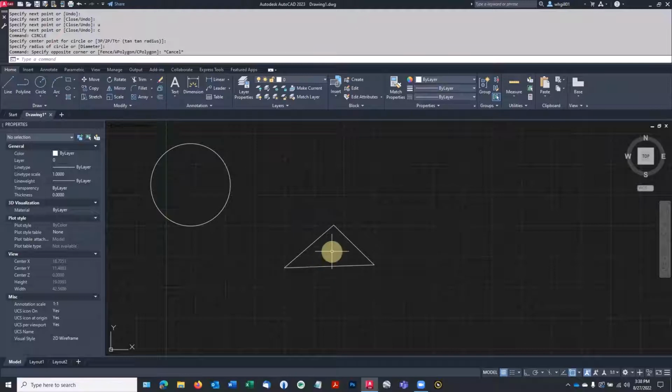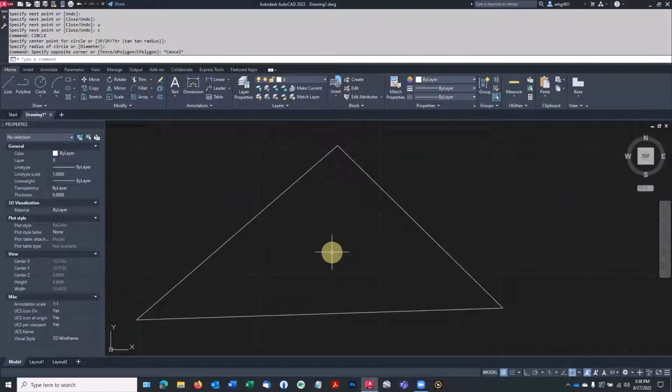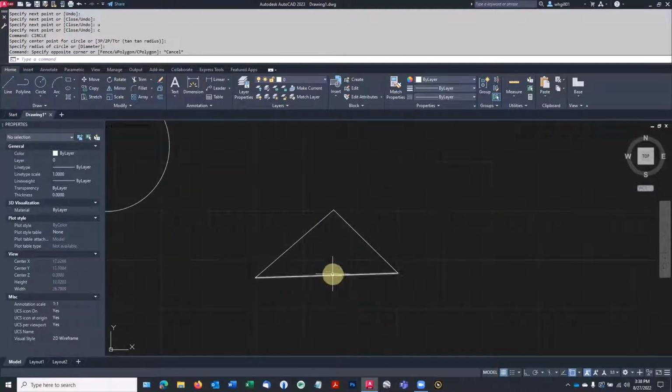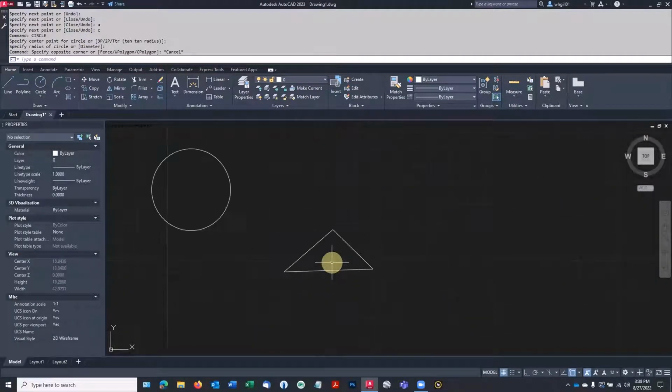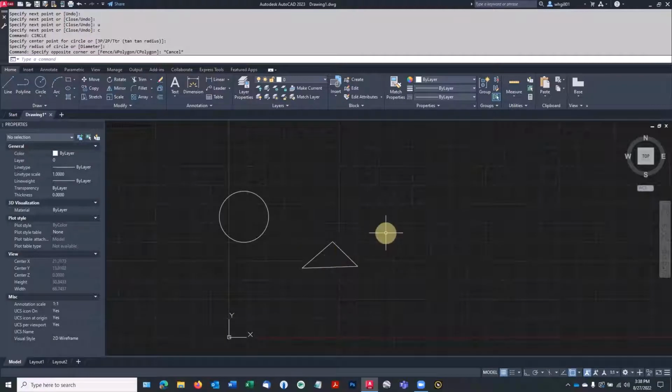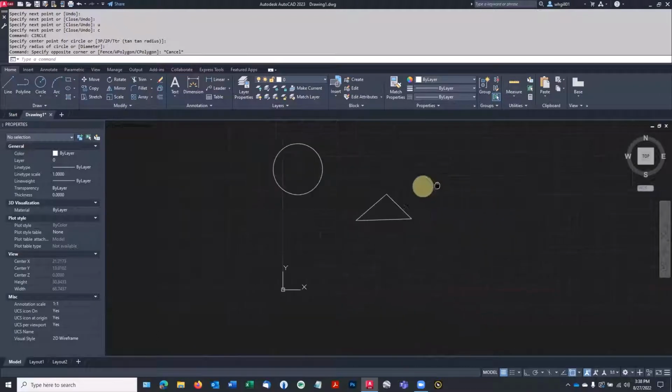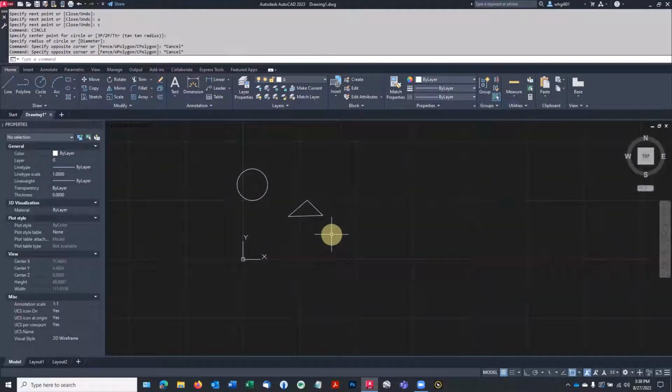The mouse wheel will zoom you in and out. Objects don't change their actual size. If that's a 4-foot long line, it stays 4 feet. We're just like a zoom lens, seeing it closer up. And also, if you hold down the mouse wheel and drag it, then we can just pan around on the screen. Zooming and panning are fundamental operations in the AutoCAD programs.